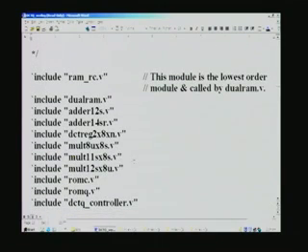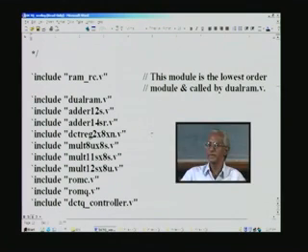Earlier, if you remember, we have seen the bottom up approach of the design, and herein we will see the reverse, that is the top down approach. In the earlier bottom up approach we started with the lowest modules such as RAM-RC, and then went on to a higher level which invoked this RAM-RC, and that higher level is dual RAM.